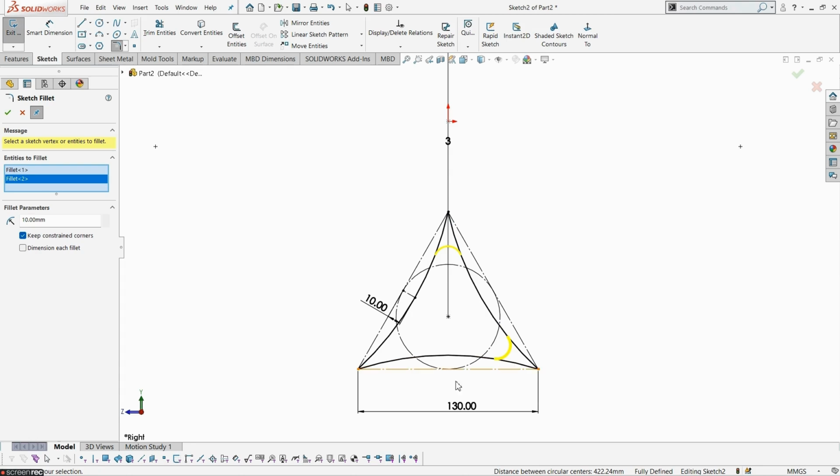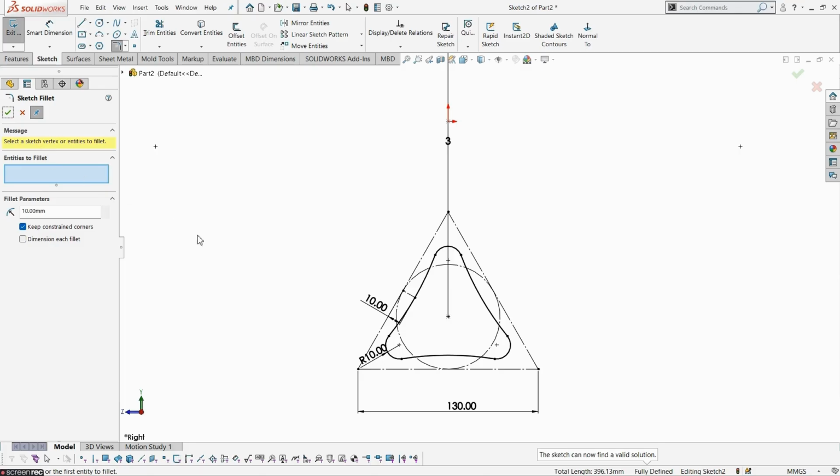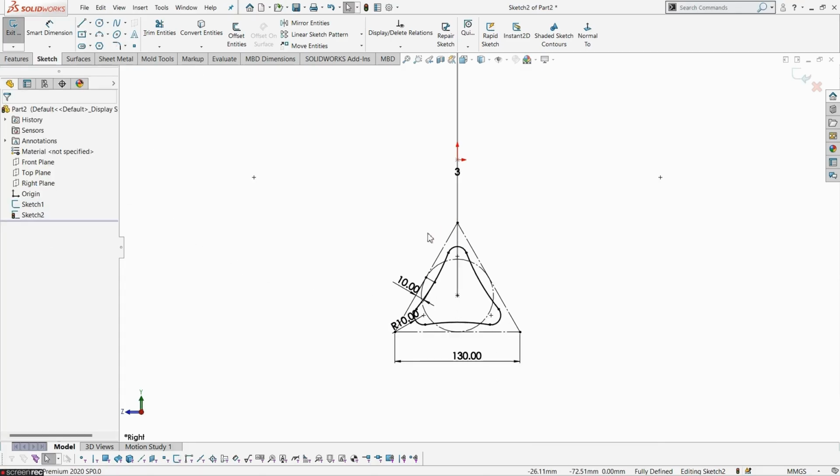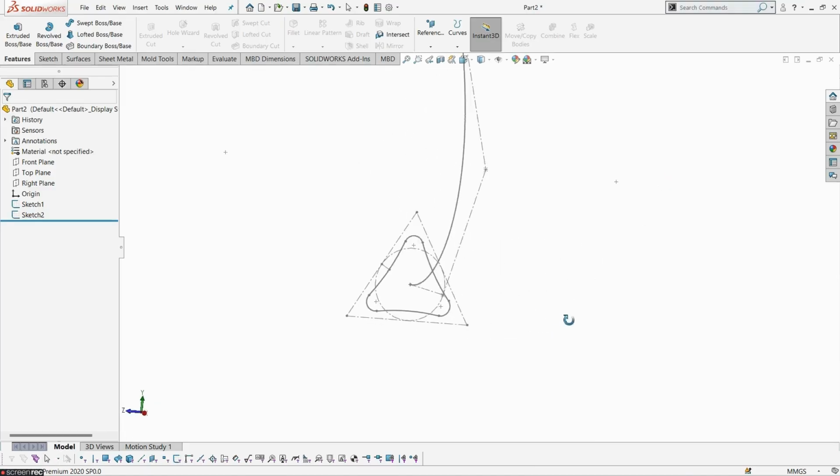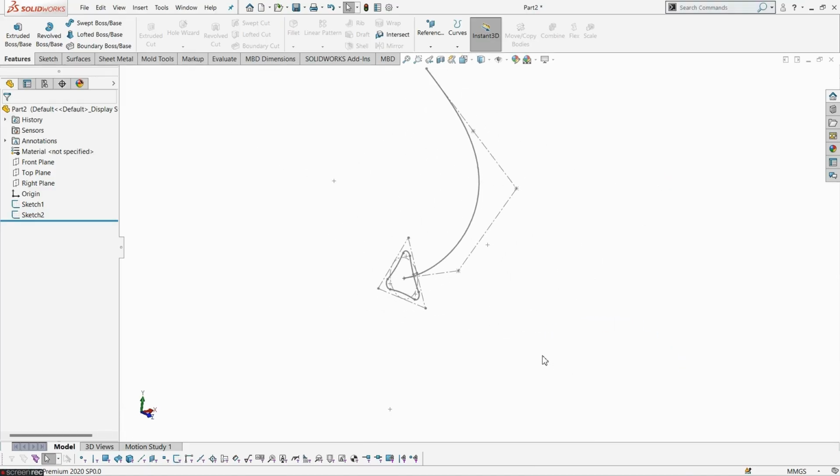Selecting a curve one by one. First one, second one and third one. Once it is properly selected, now the primary profile is created easily. Look at the dimensions of it. The overall dimension is 130 mm horizontally for the triangular profile, formed by using fillet formations.